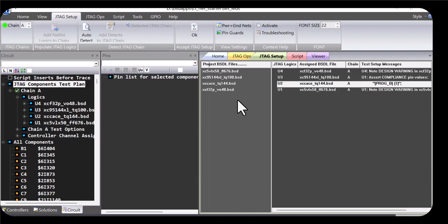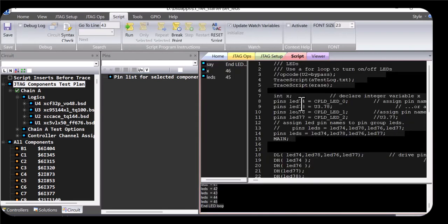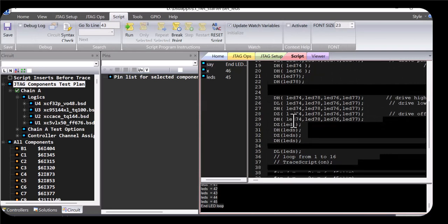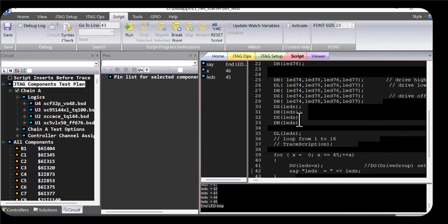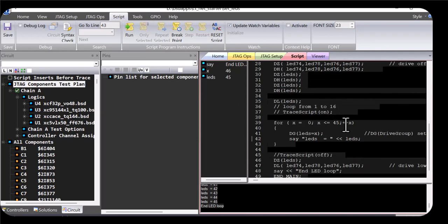So that's a quick look at script programming. It can be quite powerful. You can edit the program right here. And it's interpreted. There's no compiling, so you just make the changes that you need and run it. You can set breakpoints, as we saw. You can call functions. There's quite a bit of flow control capability involved. And it's C-like, a little bit like JavaScript, but it's very simple. And so we're going to wrap it up here. And that will be it for script programming.